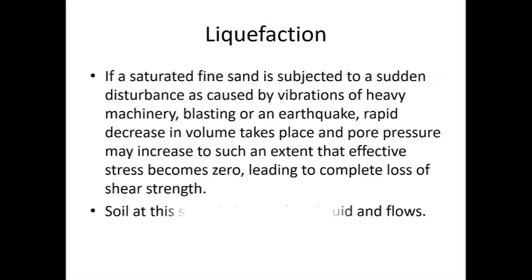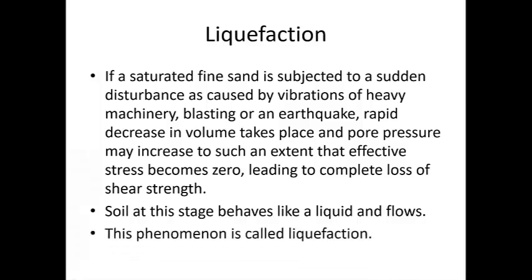So this is liquefaction. The effective stress in the soil becomes zero. No load will be taken by the soil particles and all the load will be taken by pore pressure. But if it is not confined, of course, the water cannot take that load. So the complete shear strength of the soil is lost. At that stage, the soil behaves like a liquid and it flows. So this phenomenon is called liquefaction. So watch those videos. You can visualize it better.